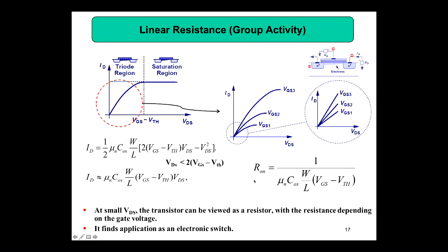Now we have studied MOS, and I am going to ask another question. You have a base current for BJT, IB. So what is the gate current for MOS? Okay, somebody already said 0. Why? Because here you are applying some voltage, but because of this dielectric material, no current can pass through. So the gate current is equal to 0 for MOS.